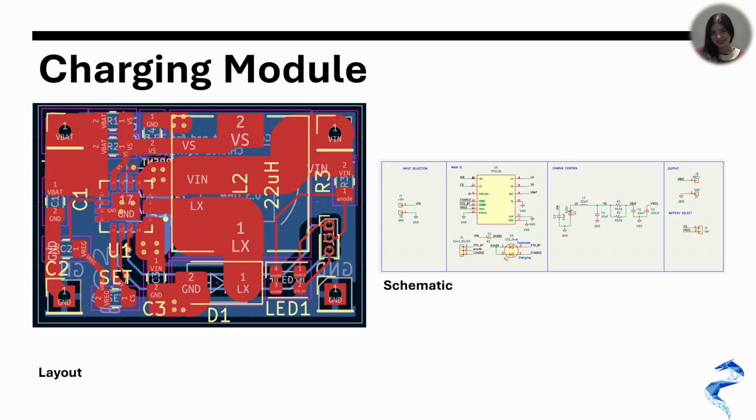We also included LED indicators to show charging status. In the PCB layout, high current traces are kept short and wide, and grounding is carefully routed to minimize noise. Overall, this module ensures safe, efficient charging with proper voltage control and clear user feedback.